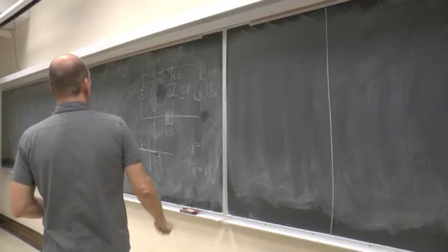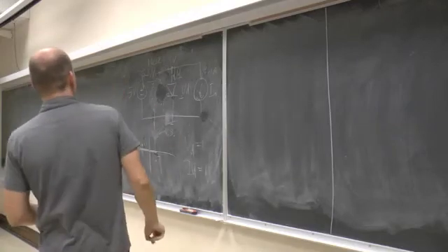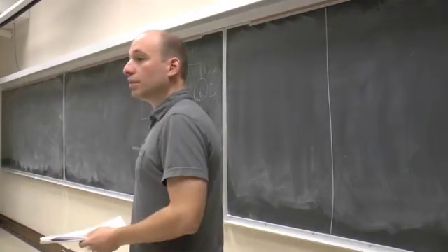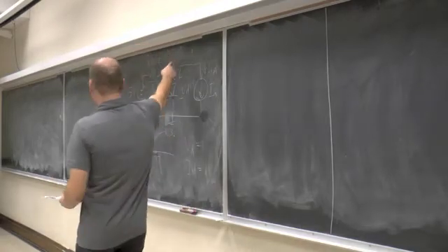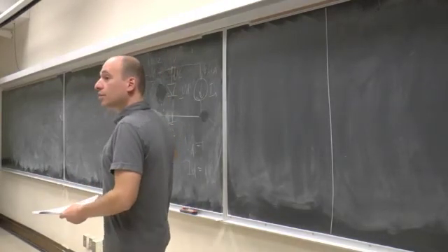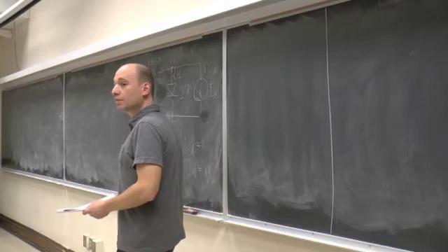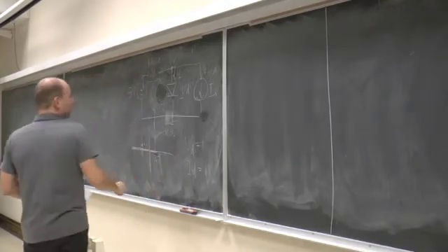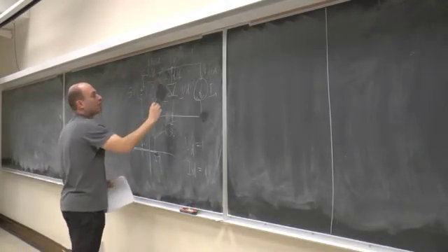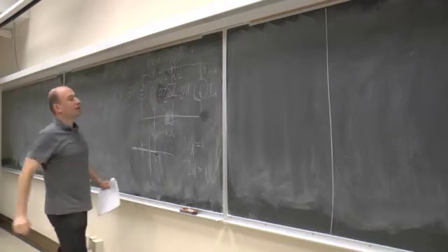And what's going to happen to the diode? The diode now is forward biased, right? So what is it going to behave like? It's going to behave like a voltage source. So now we can write 0.7 volts on the diode.